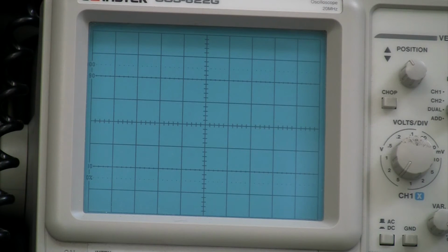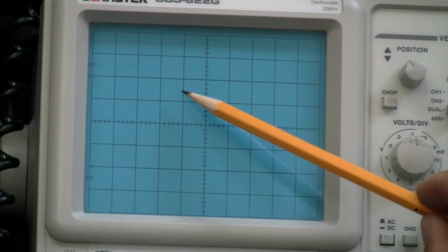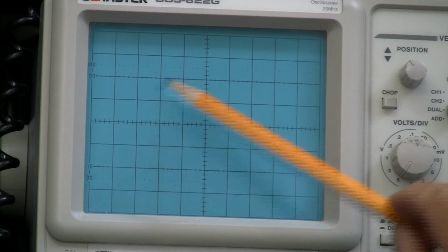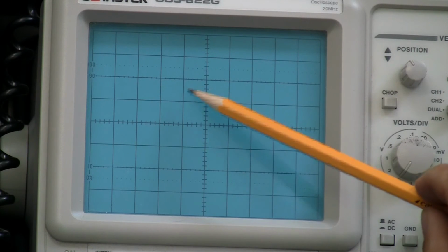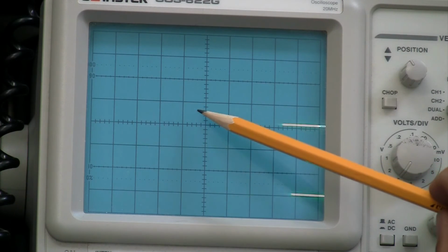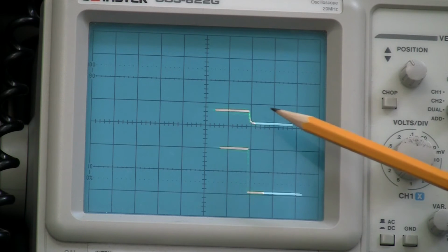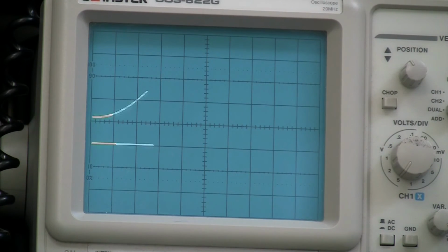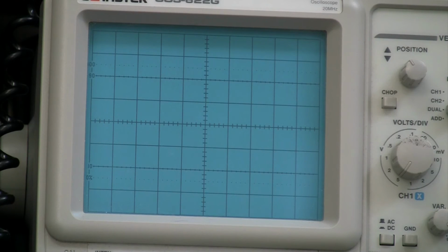I'll point out something else which you might find useful. Right now we have an attack phase that's now concave. Remember, a normal ADSR envelope actually bends the opposite direction. Now we have a concave ADSR. But if you look closely, the decay segment and the release, which if you remember were both set to 0, are actually now faster than they were before. And this is not a surprise also. Given the nonlinear shaping of this amplifier control input, it has the effect of bending these waveforms and making them steeper on the falling side and shallower on the rising side.